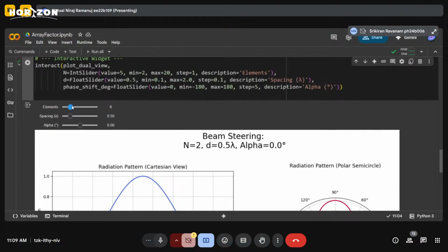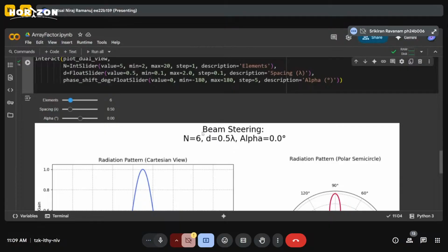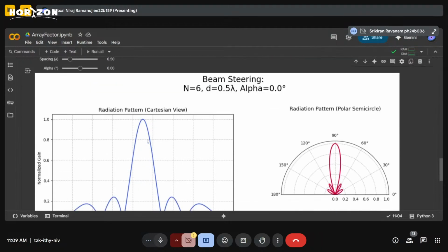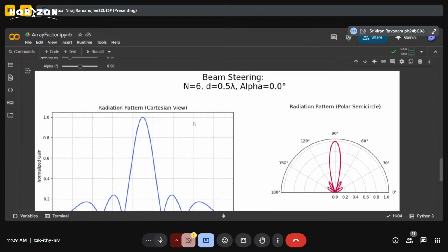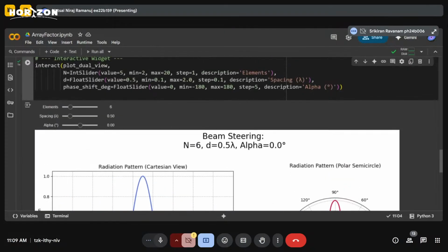Now, one more thing that we can control during our construction is how far apart the antennas are situated. Usually, this number is kept at half the wavelength because that gives us very good, well-behaved graphs. This is not a hard and fast rule. In our derivation also, we could have put d as any value. We could have derived the array factor equation, and we could have plotted it very easily.